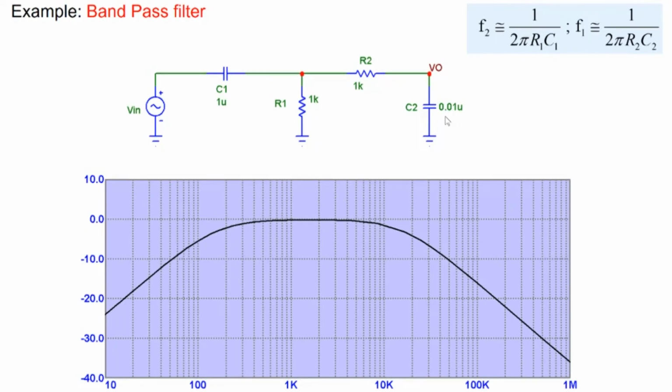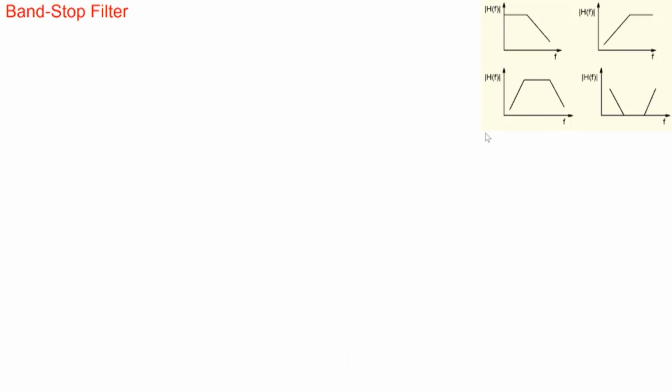And you can check it out by sketching your own Bode plot: that particular filter would have provided you with more attenuation in the band in which you don't want frequencies to pass. So it would have been a better filter in that respect, a filter which attenuates the unwanted frequencies.